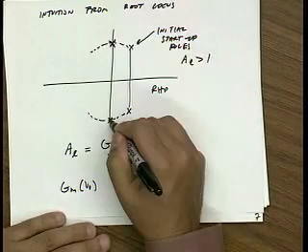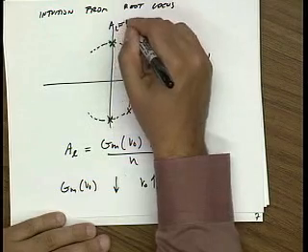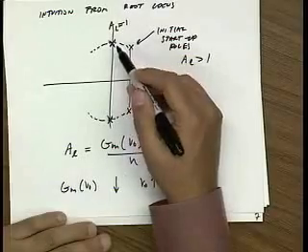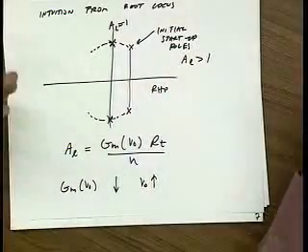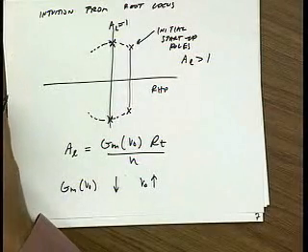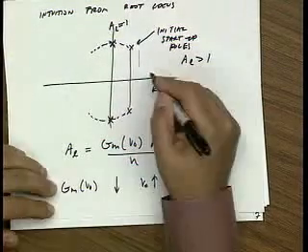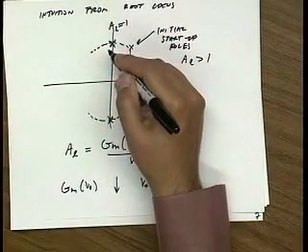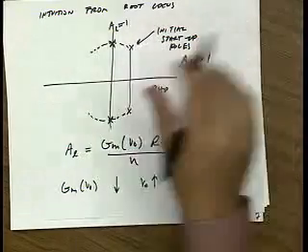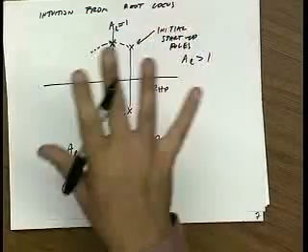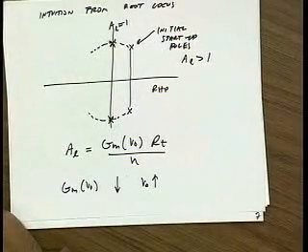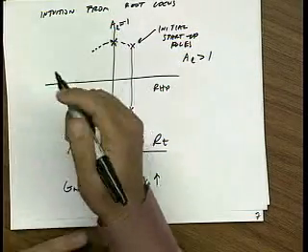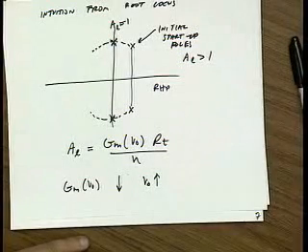And when they hit the j omega axis, loop gain is exactly equal to 1, and they just stay there. Because once they hit the j omega axis, the poles don't grow and they don't decay. So they just remain constant, right? And so that gives us some intuition for why no matter where we start in the right half plane, they just keep moving left until they hit that j omega axis. That j omega axis is a steady point because the amplitude doesn't change anymore. And there's perfect energy balance occurring there. Well, what happens if I somehow or another disturb the system, right? Let's say the disturbance causes the poles to move to the right half plane.